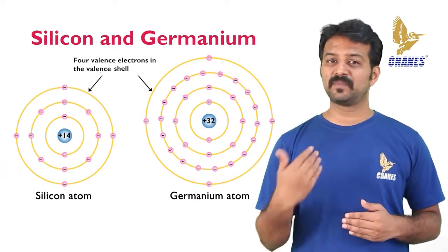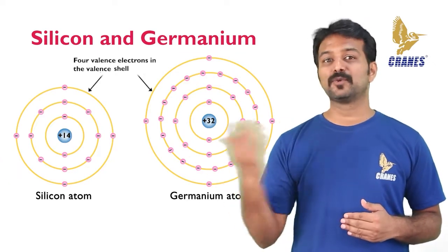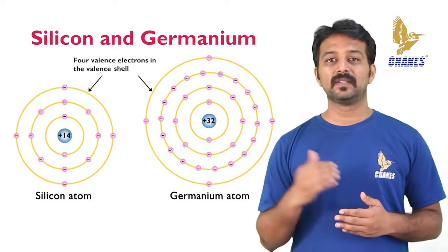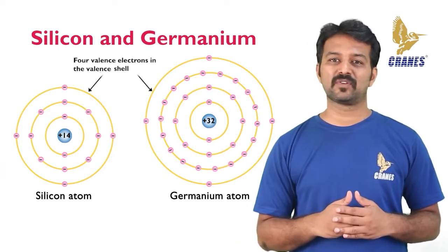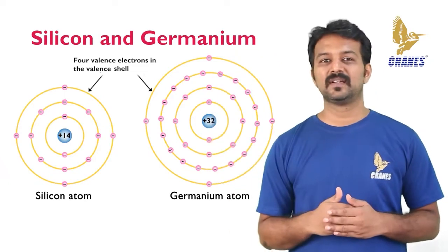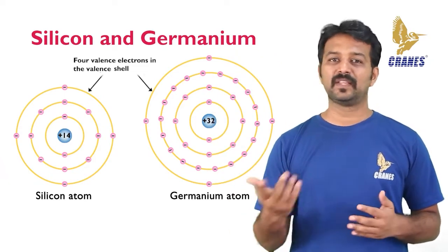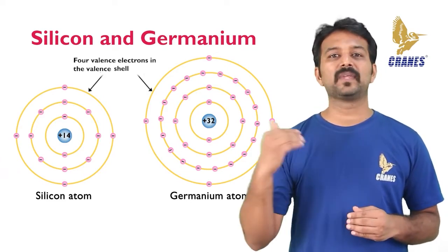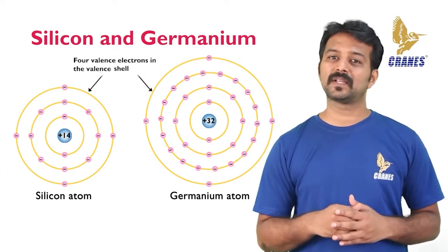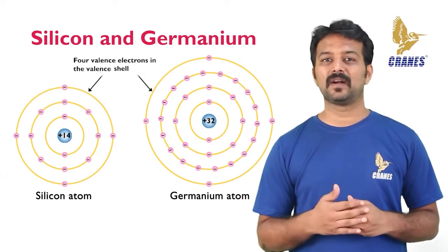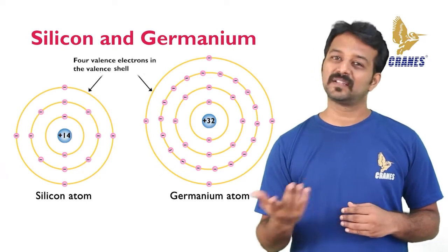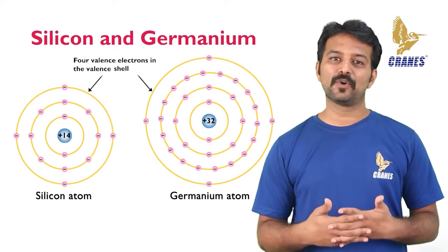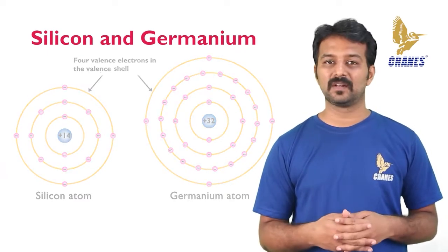The valence electrons in germanium are in the 4th shell, while those in silicon are in the 3rd shell, which are closer to the nucleus. This means that germanium valence electrons are at higher energy levels than those in silicon and therefore require a smaller amount of additional energy to escape from the atom. This property makes germanium more unstable at higher temperatures and it results in excessive reverse current. This is why silicon is the more widely used semiconductive material.